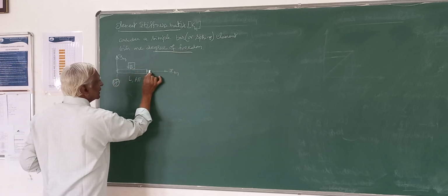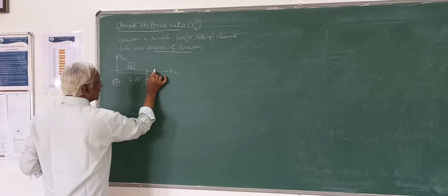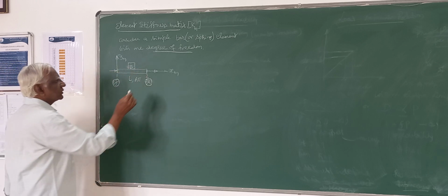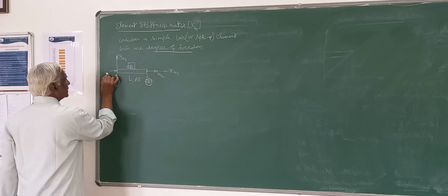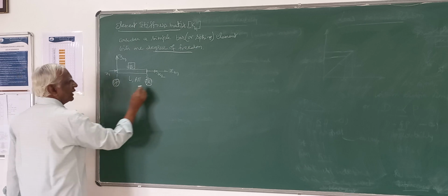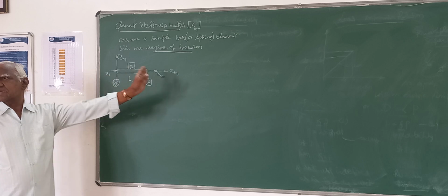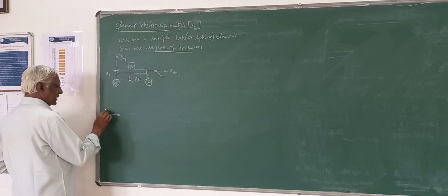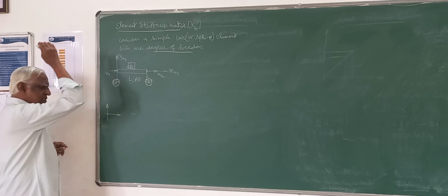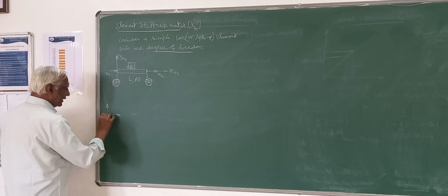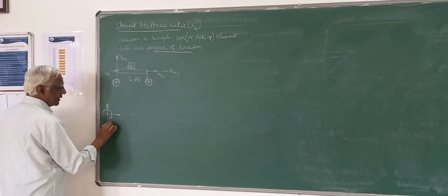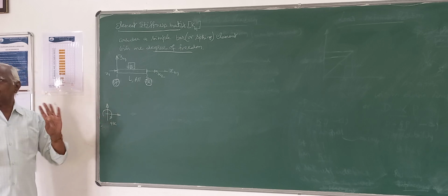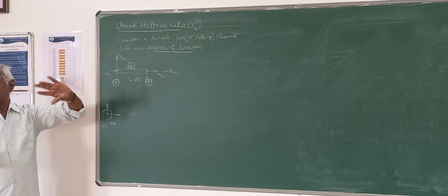So here the degrees of freedom are the displacements only at the end points. Generally we take the positive direction along the coordinate system like that. So this is one displacement, the displacement at 2, which you can call displacement 1, and the positive direction is always left to right. That is another important thing, sign convention. Always we take left to right as positive for forces, bottom to top as positive, and rotation in the clockwise sense as positive. This is the sign convention we normally adopt, because we are dealing with a maximum of 3 degrees of freedom, as we analyze planar frame structures.